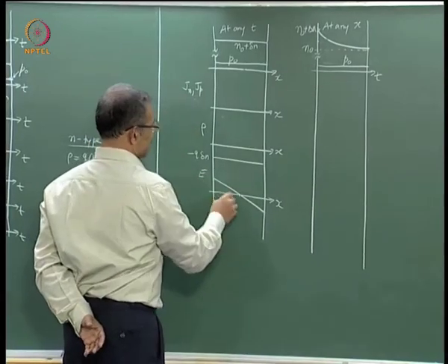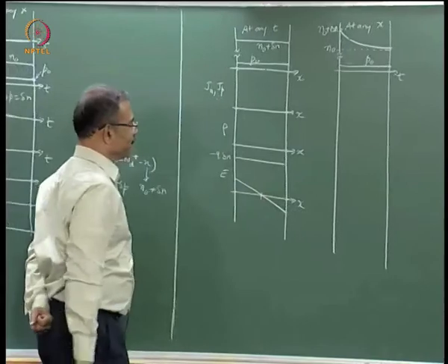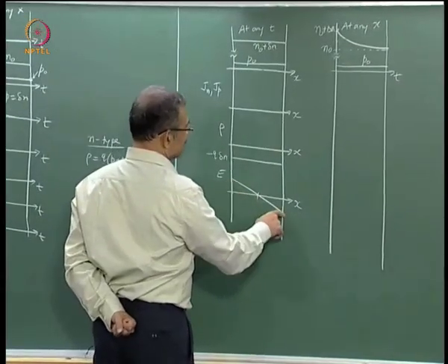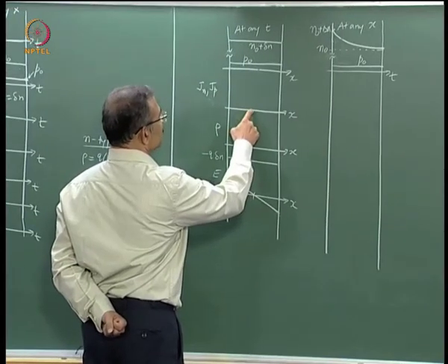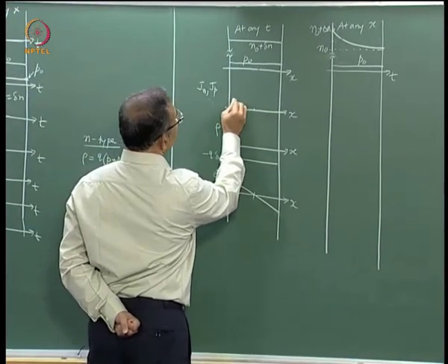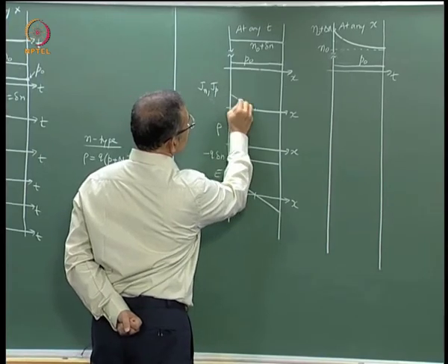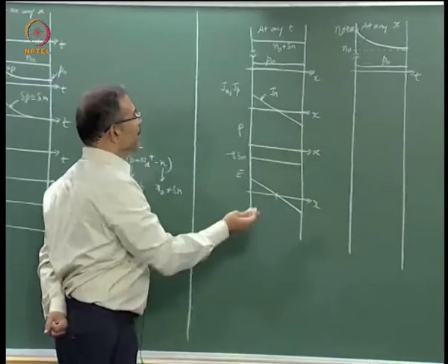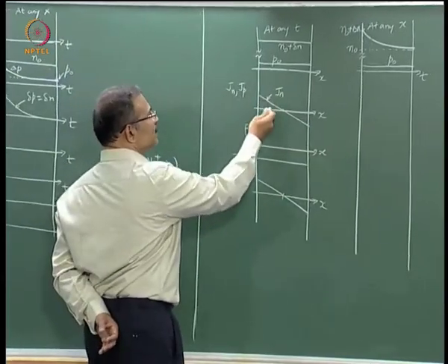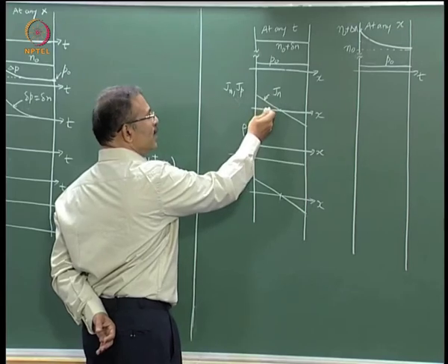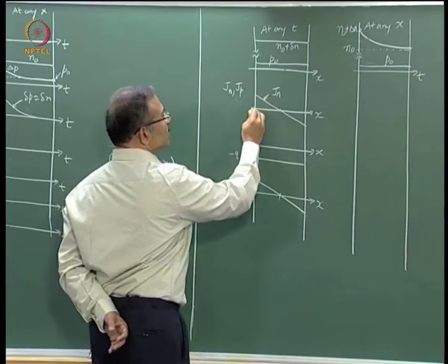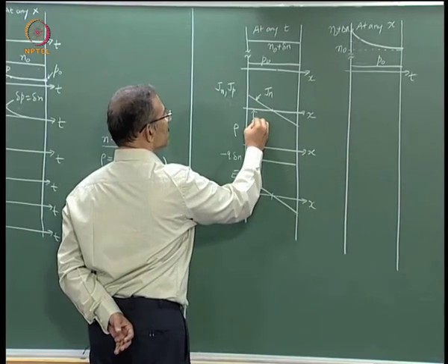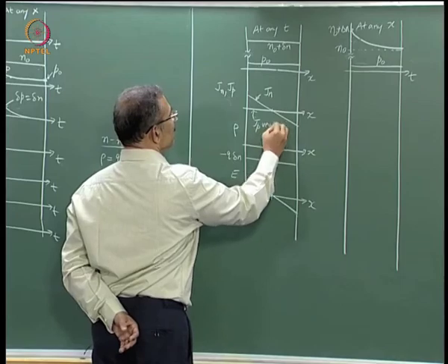So this is E versus x, linearly varying. Now because E is varying like this, the current because of this will also have a similar variation. So this is, suppose, Jn. Jp we really cannot show on the same scale because hole concentration is orders of magnitude less than electron concentration. So really Jp is negligible. So we cannot show Jp. We will just say Jp is very small.